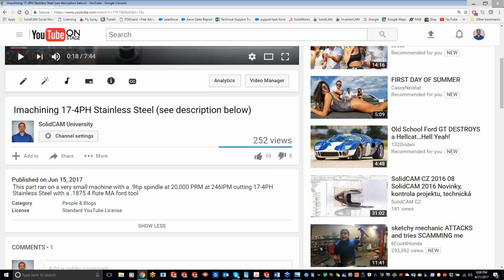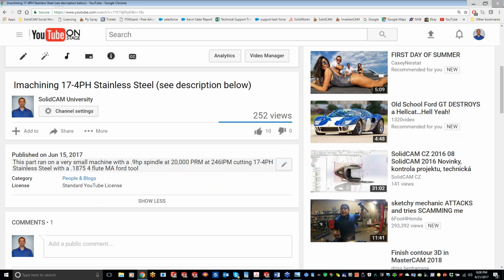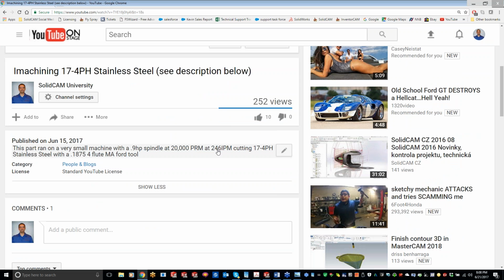It's a Defiance VTX-1, specially made just for wood. But we did 246 inches a minute, cutting that 17-4 stainless with a 3/16 4-flute MA4 tool. So really kind of cool there.